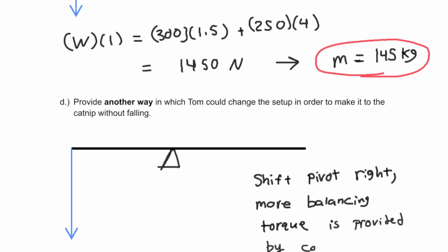Because if we put that counterweight all the way on the left end, assuming it's large enough, like it's over 200 pounds, it's hard to move. Well, you could just move the pivot. So again, if you double the distance that the pivot is, that's going to increase the amount of torque provided by the same force. And also that's going to decrease the torque provided by everything else.